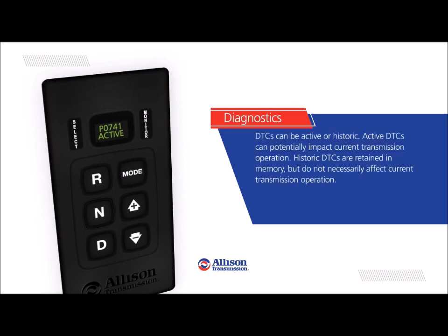DTCs can be active or historic. Active DTCs can potentially impact current transmission operation. Historic DTCs are retained in memory, but do not necessarily affect current transmission operation.